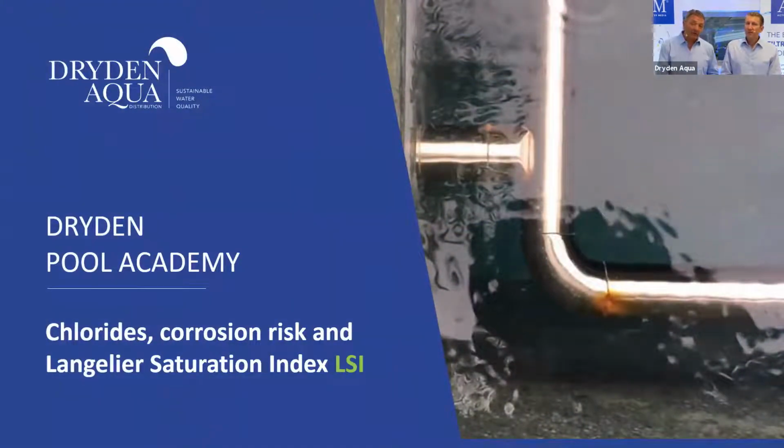So what is the downside of it? First of all, a lot of people say, well, DHN, this is a no chlorine solution. There is no chlorine. This is wrong. It's a low chlorine solution. And it's also not a non-corrosion risk. It's a low corrosion risk. And really the risk is in your hands, and you have the responsibility to make sure that you don't have corrosion. And this is why we come now to corrosion risk and to chlorides, etc.